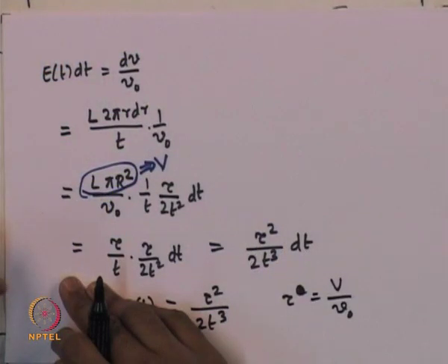Now the question is, what is the validity of this expression? Or, when will the fluid start leaving? Suppose I put a pulse tracer at the entry of the reactor. How much time will it take for this tracer to first appear at the exit stream of the reactor, and what will be the first time at which the fluid actually leaves the reactor at L? This is important because E of t is essentially the age distribution of the effluent stream.